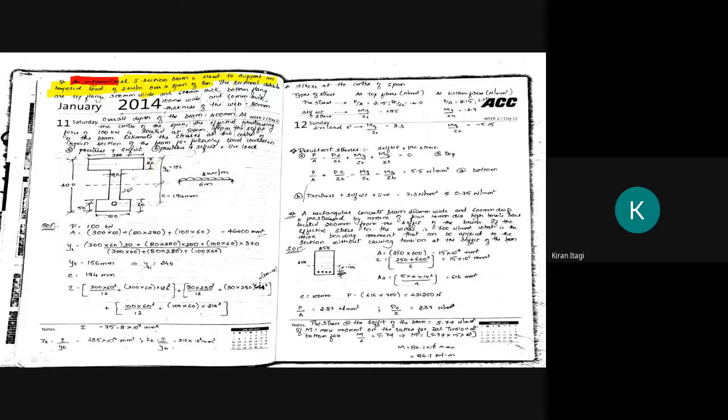and live load. Okay. The sectional details are top flange. What do you mean by top flange? This is the top flange. Okay, this one is the web, and this is the bottom flange. Therefore, the section details are top flange of 300 mm wide and 60 mm thick. The bottom flange 100 mm wide and 60 mm thick, and the thickness of the web is how much? 80 mm. Therefore, the top flange, web and the bottom flange he has given. Overall depth of the beam is how much? 400. So he has given this overall depth, that is 400 mm.